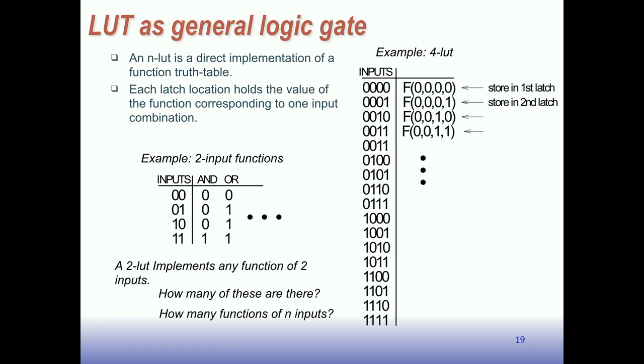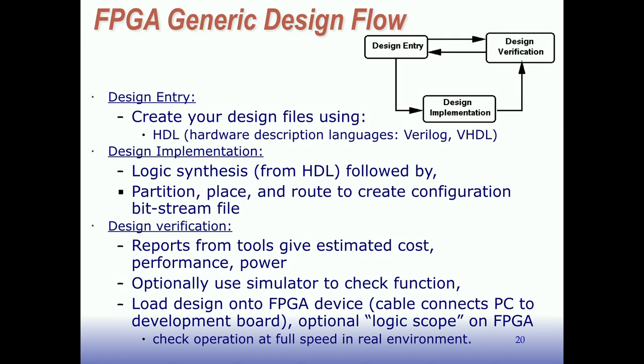Okay, so that's the basic idea behind the internals of the FPGA. You can see now how you can make programmable interconnections, and how you can make logic blocks that can be any functions that we want. The goal of the tools, after they take your Verilog and synthesize it down into logic gates, is to cut this big network of logic gates up into subfunctions, where each subfunction, a collection of logic gates, can fit inside one of the LUTs. So this is the generic flow here.